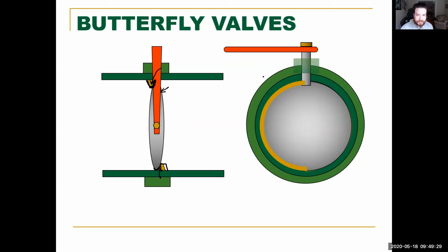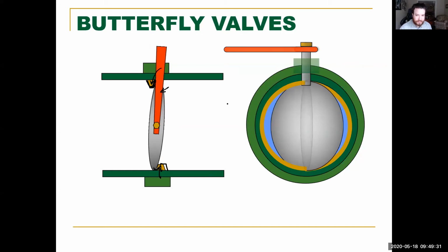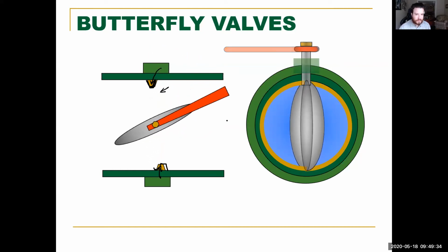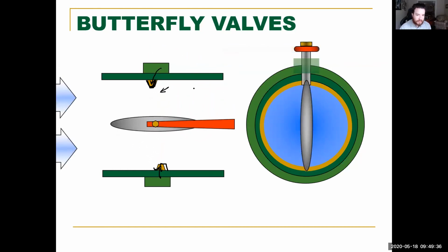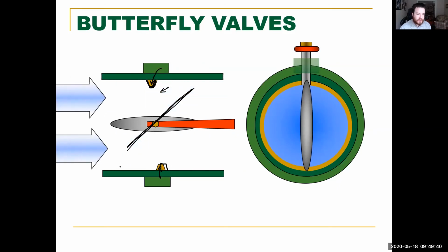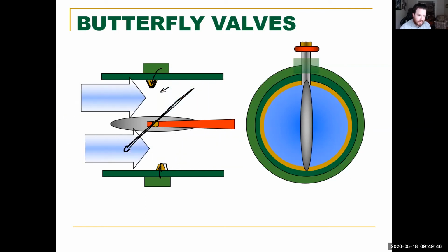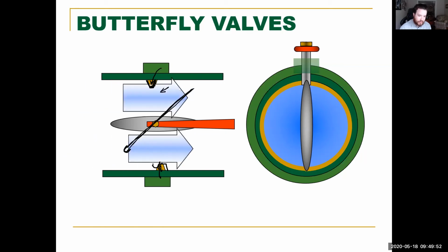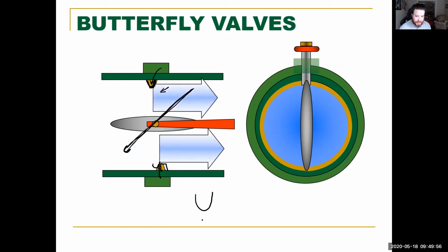So when they open, and if they're in a throttle position where they're like this, that wear isn't going to matter too much. Because if it starts to wear off, it's just going to seal here. And it's the pressure from the disc to the seat that's going to be sealing it.